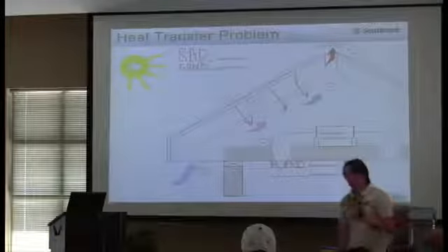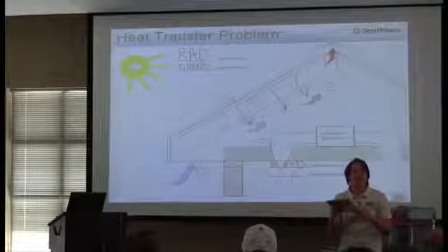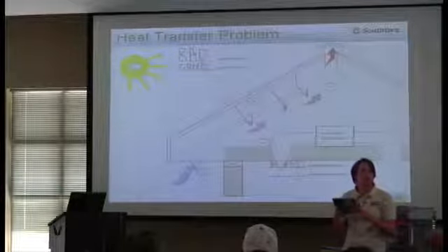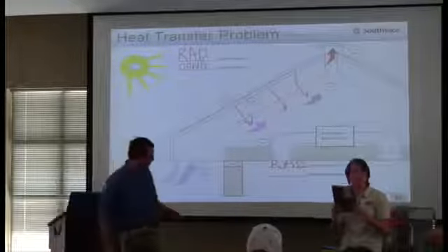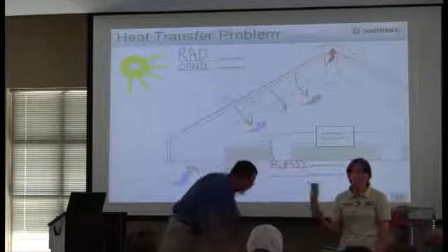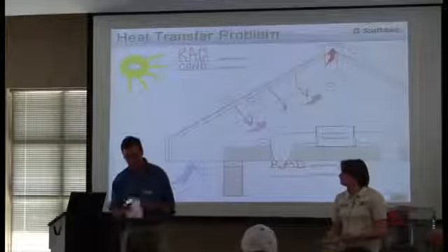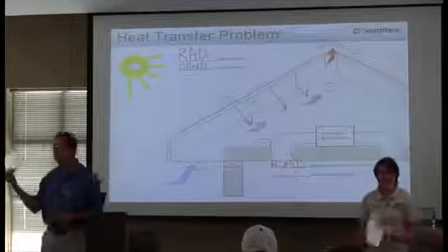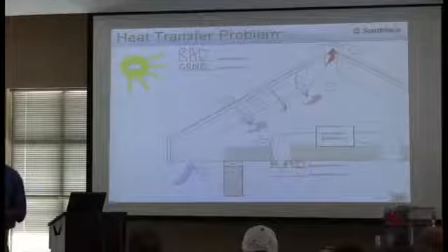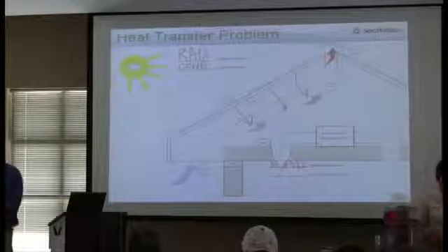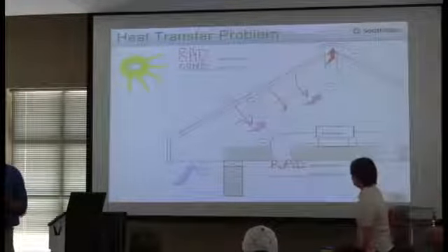So this is a good product, especially if you have your air handler up there and you can't afford to spray foam the roof line or insulate the roof line. This is fairly cheap. It's almost the same price. They do make retrofit products. Some have this bubble wrap on them, which is kind of meaningless, I'll pass it around. But they also make some that are basically aluminum foil, and they've got little holes in them, so they're not going to trap moisture.